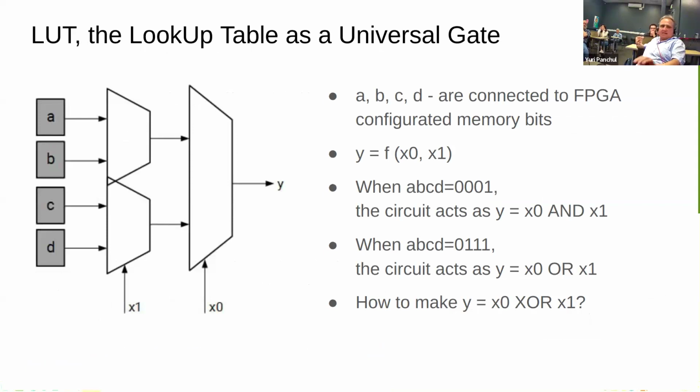You can just set up zeros and ones in memory connected to a multiplexer, and suddenly this element behaves as an AND element, another as an OR element, another as 1 bit of memory storage. And you can essentially put any circuit inside this chip, including a CPU.